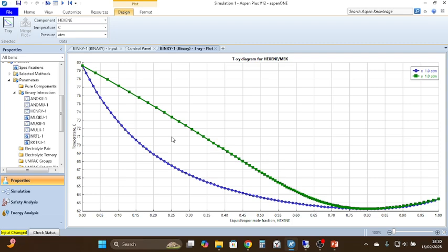Now keeping the pressure fixed, if we increase the temperature, then it is going to move upwards. Then this is the point at which you are going to get the saturated vapor, at a temperature that lies between 73 and 74, and the corresponding temperature of the mixture will be obtained from here.